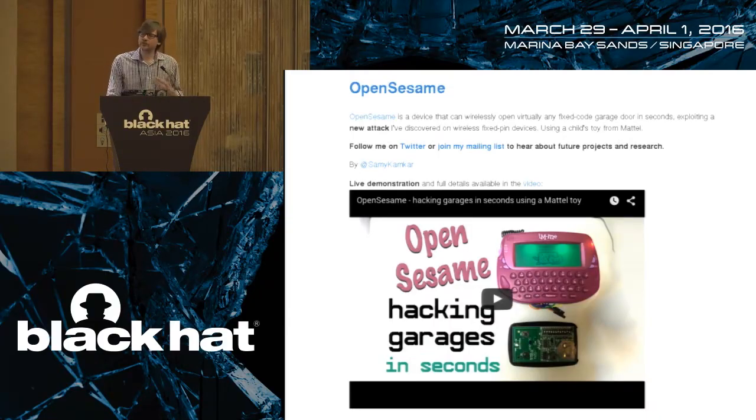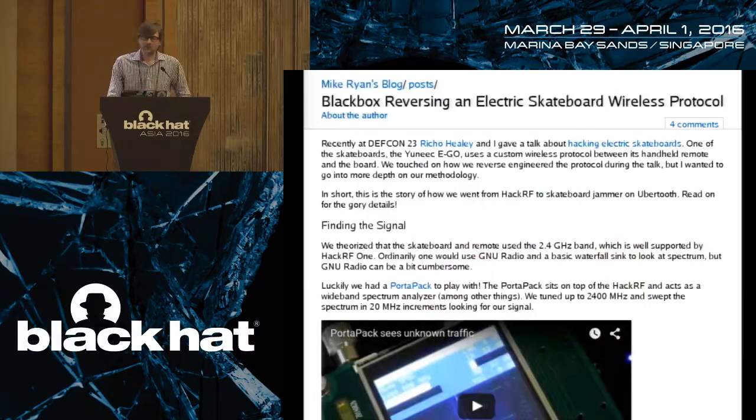But as he was reverse engineering remote keyless entry systems for this research, the approach that he used was exactly what I'm showing you today. He used SDR as his initial recon to figure out what radios were doing approximately, and then learn the physical layer characteristics. And then once he acquired those physical layer characteristics, he turned to Yardstick 1, just like I'm going to do today. And he used Yardstick 1, and also some other wireless transceiver IC platforms, to implement the attacks.